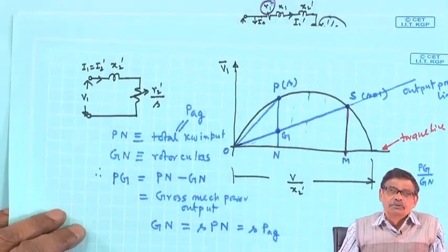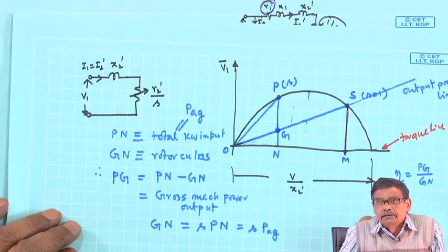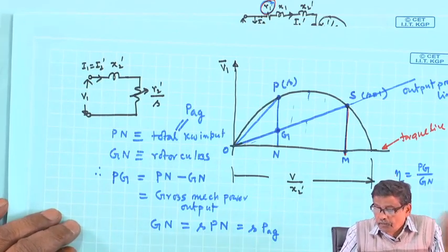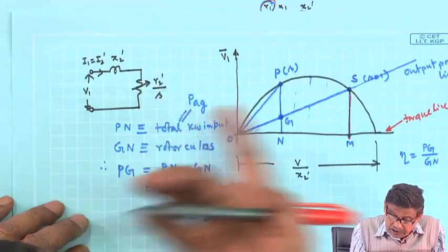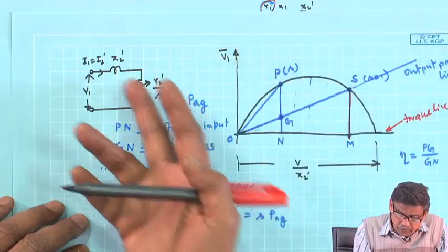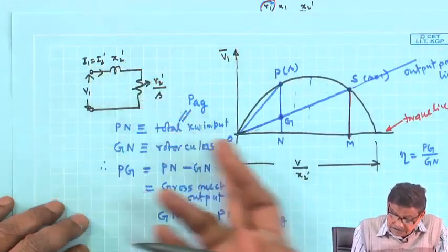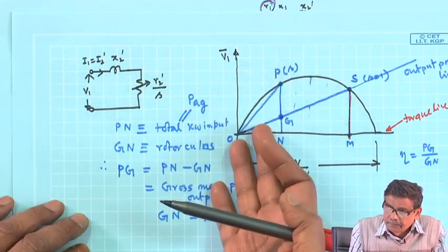What am I supposed to do? That is, okay, the machine is running at slip 0.08, find out its output power, input power, things like that. Then what do I have to do here? Here also I have not drawn any other slip line. I have to at least calculate once what this theta is, fix up the operating point, then tell everything.